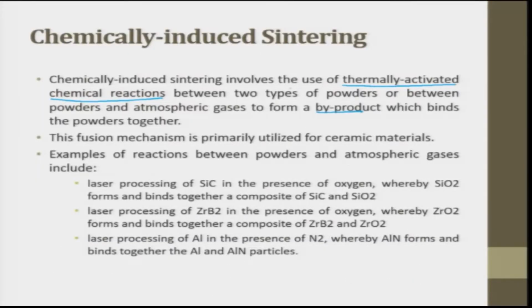Okay. In chemically induced sintering, what we do involves the use of a thermally activated chemical reaction. Here there is a reaction, but in the laddu example there is no reaction. Thermally activated chemical reaction between two types of powders, or between the powder and the atmospheric gas, forms a byproduct which binds the powder together. This fusion mechanism is primarily utilized for ceramic materials only.